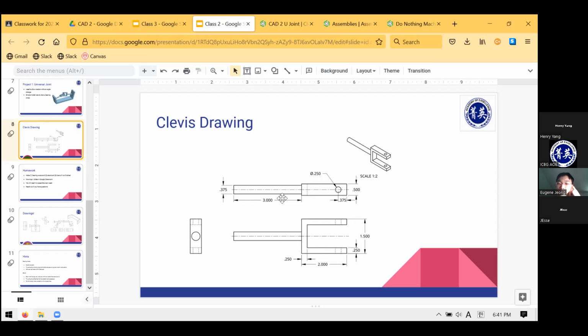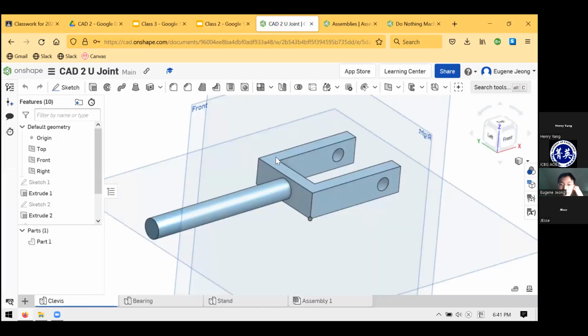On these other 2 views of the object, when you look at the side view here, this feature that you're interested in, this rod, has a dimension here of 3/8 of an inch. You can imagine if you flip this view, it's the same thing as dimensioning the diameter of this circle. So that tells you what the rod should be. You can see it is 0.375.